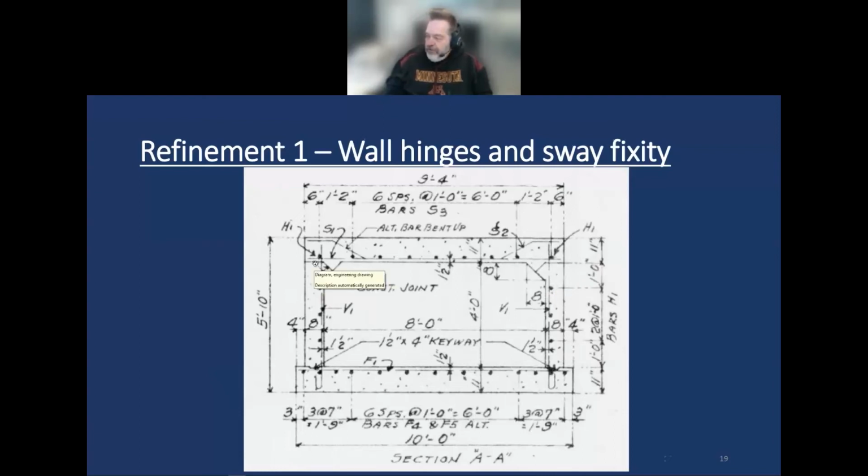If you check the moment release at the top and at the bottom, it basically turns this 4-sided structure into 4 simple span beams. And make sure you check the sway prohibited box as well, otherwise it becomes a mechanism, and that's not good for structural analysis programs. What you want to do is turn all your live load from on top and all your dead load from on top into a simple span beam, and you do that by putting a hinge here, and then at the bottom as well.